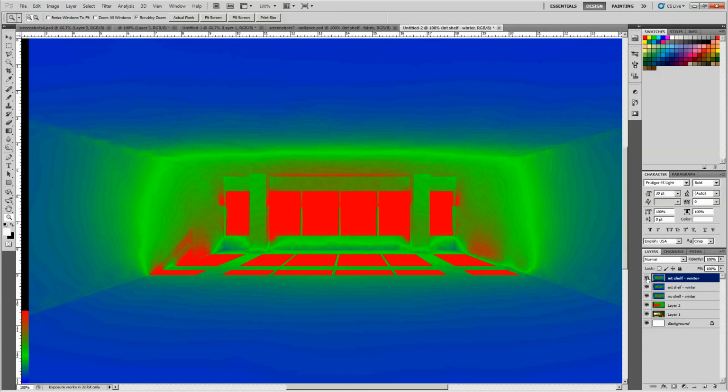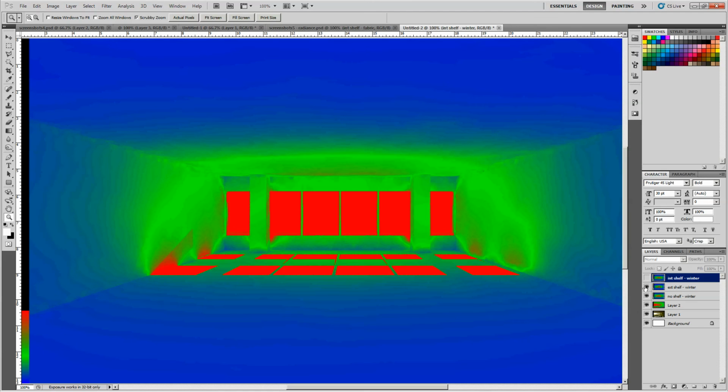So that means that there's actually light being reflected off the interior light shelf that hits the ceiling in a more effective way than the outside. A lot of the outside is actually reflected up against the top window portion, that top portion of the wall that's not a window. So that's kind of a fault of this design. I mean, it would be better if this window was actually all the way to the ceiling, and then maybe an exterior light shelf could still be valuable.